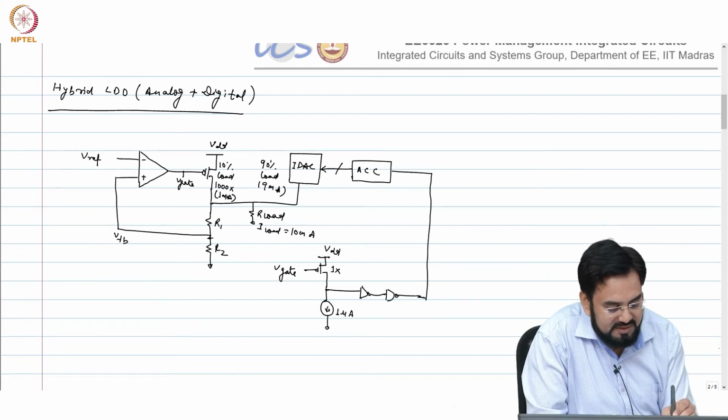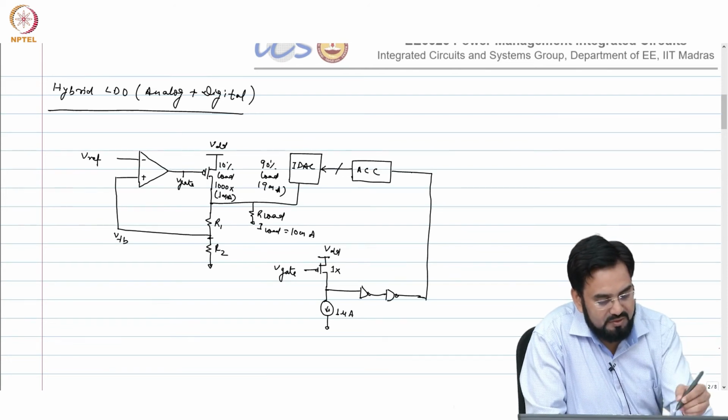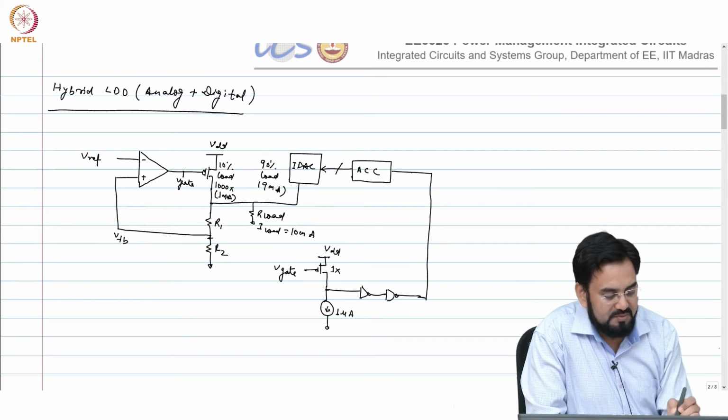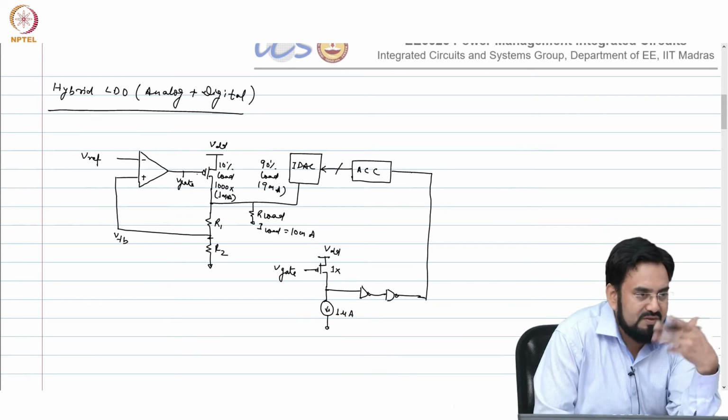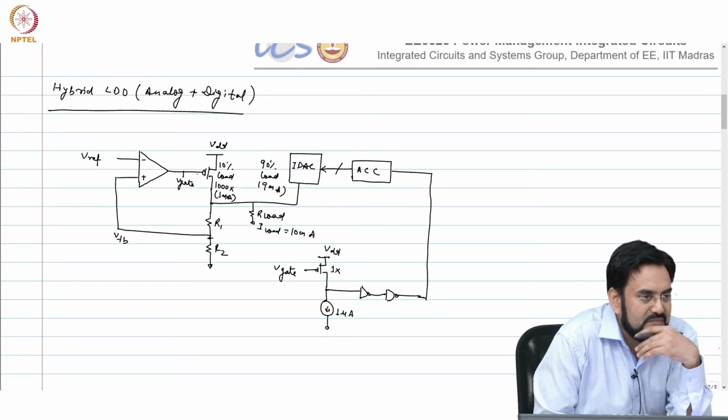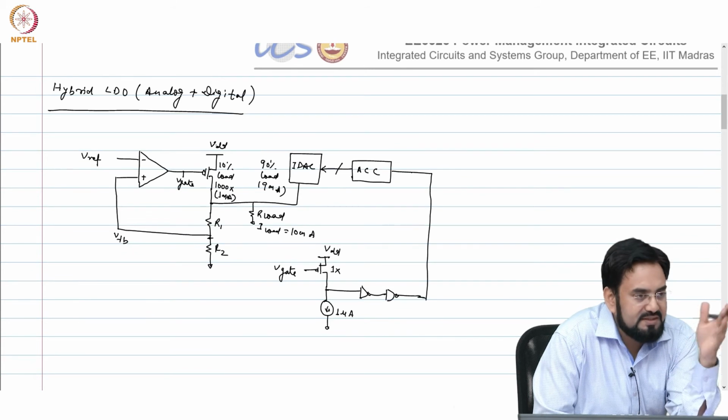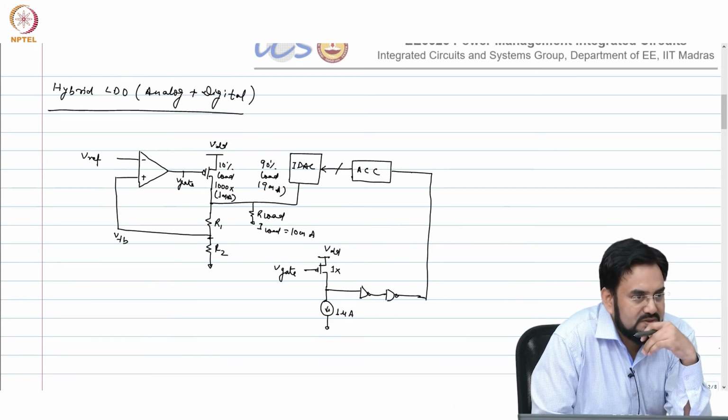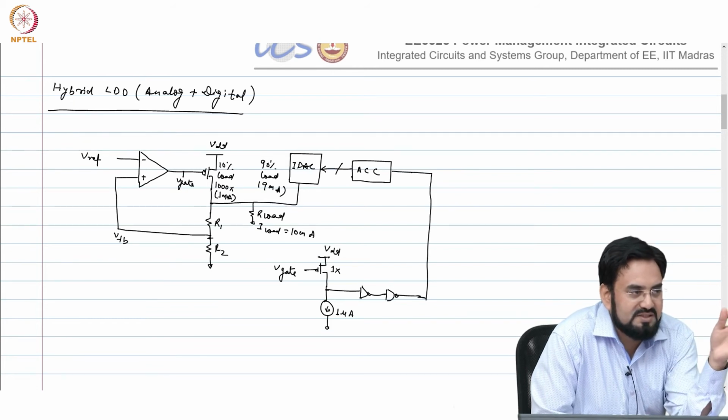But consider the short circuit case where you have connected this output to the ground, and so we know that you have sized your device for 100 millivolt overdrive, and now let us say VDD minus VGS, the difference becomes 1 volt. So 100 millivolt now 10 times increase, and you know that's a square. So your size is same, mu C ox is same.